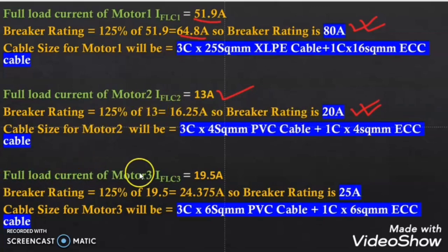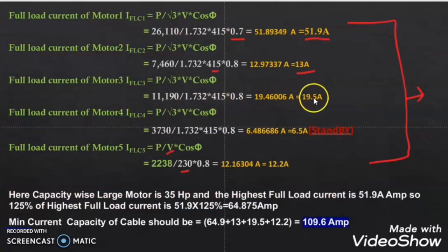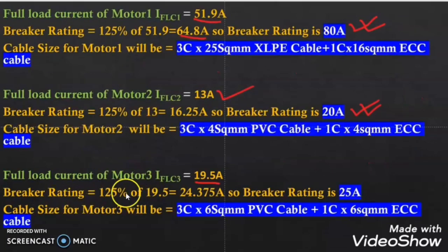In the same way, for motor 3, the full load current rating came as 19.5 ampere, which I will show you here, for motor number 3. So the breaker rating will be 125% of 19.5 ampere, which came as 24.375 ampere. The next standard available size breaker is 25 ampere, so we will select a 25 ampere breaker for motor 3.